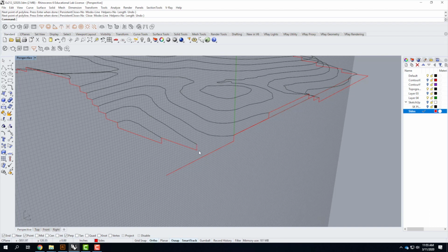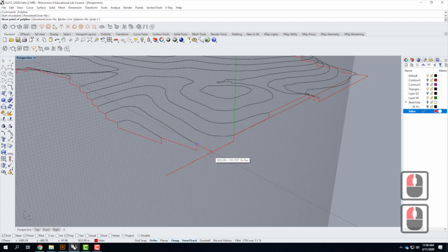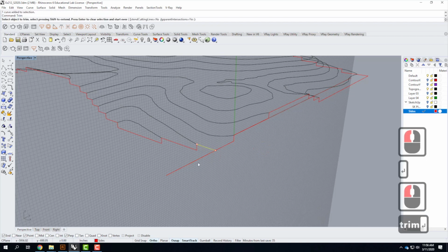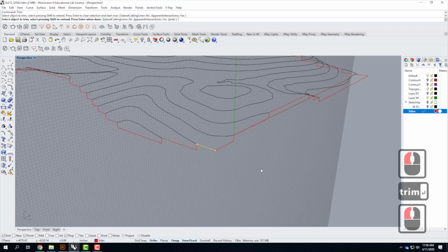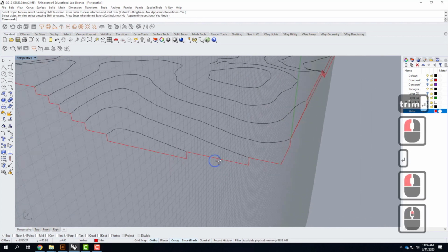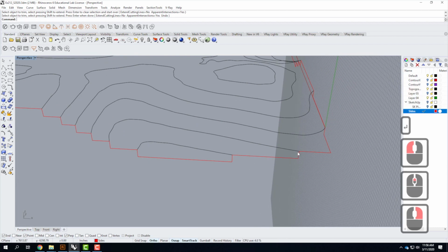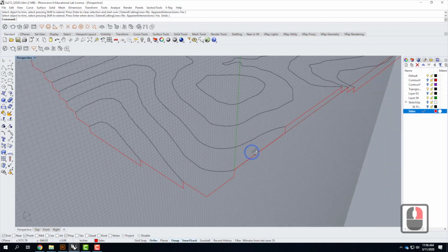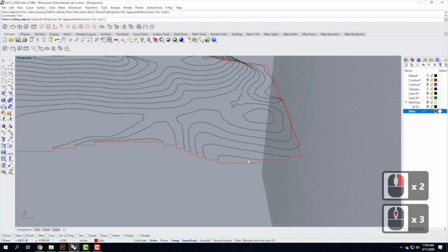So what I need to do is I need to extend this line from this point over to meet that. So I'll go ahead and snap here, and then snap to perpendicular there. And then I can use that as a trim for that piece as well. So the step is occurring around the corner. So I step up, I turn the corner and go back, and then I step up again. So you're always kind of double checking as you work.